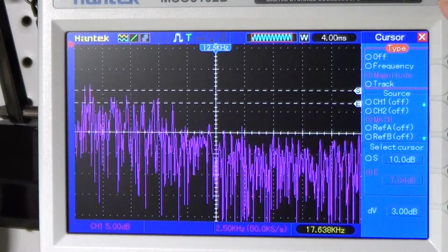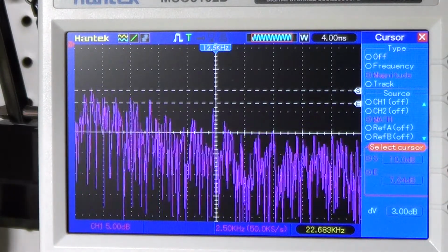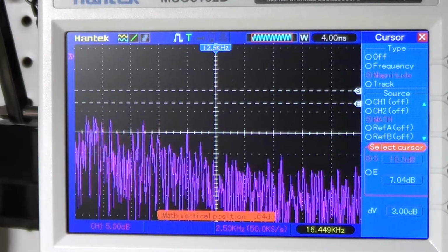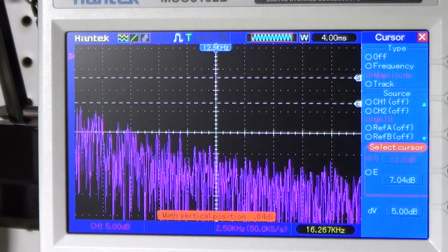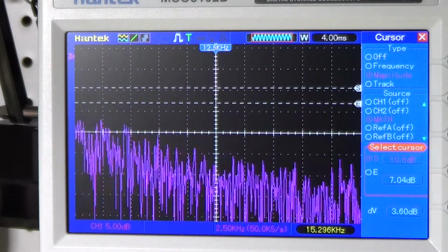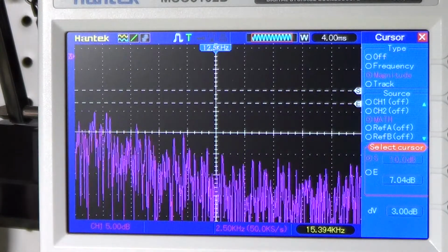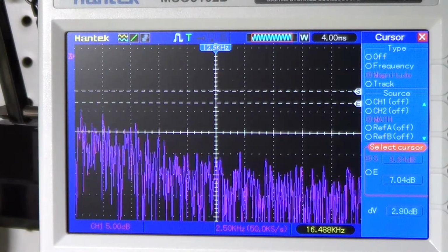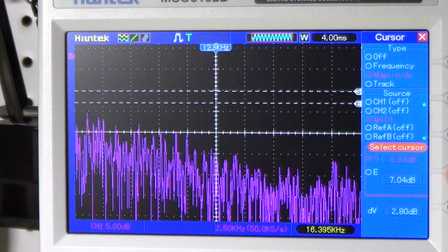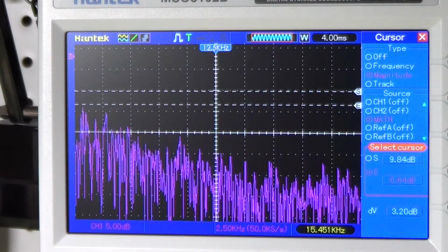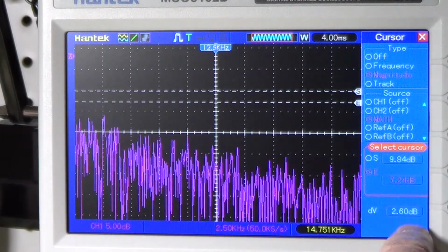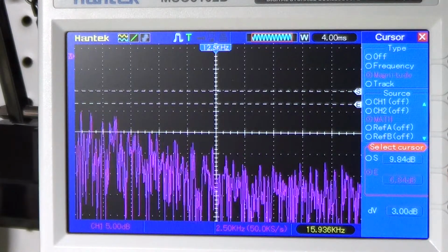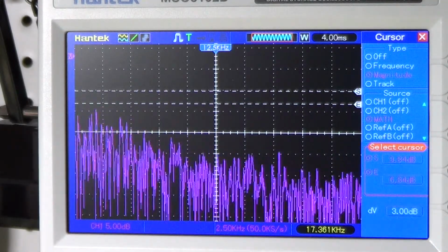So let's start with the first cursor, the start one right here. Let's adjust it right here, so it'll be easier to make the measurements right on the line represented by the oscilloscope. And then the second one, which is going to be 3 dB lower, so we can read it from here. And now let's lock the cursors so they won't move anymore.